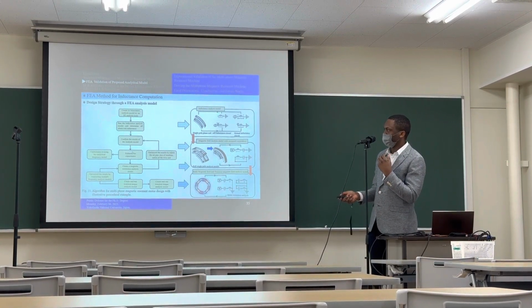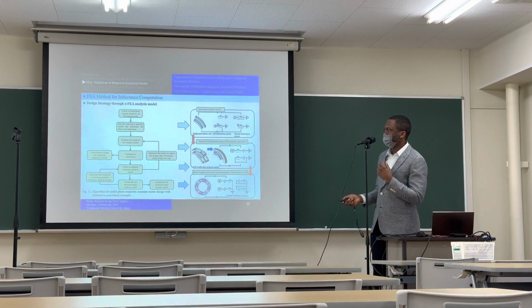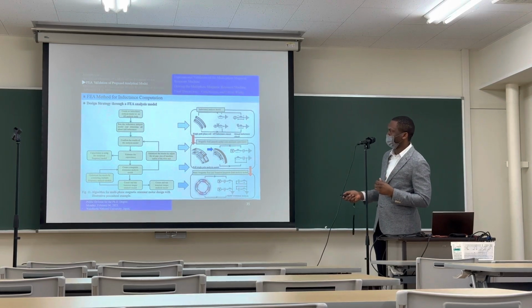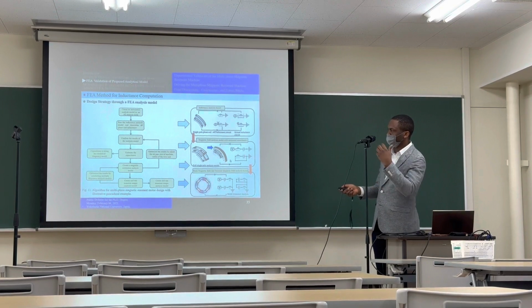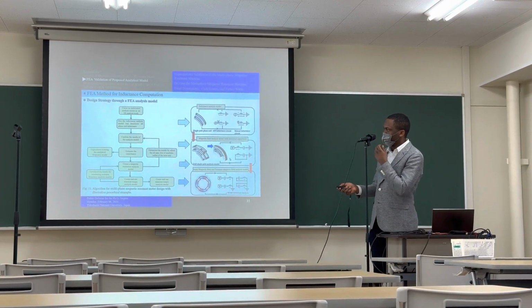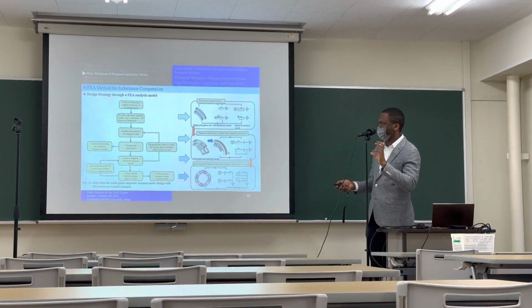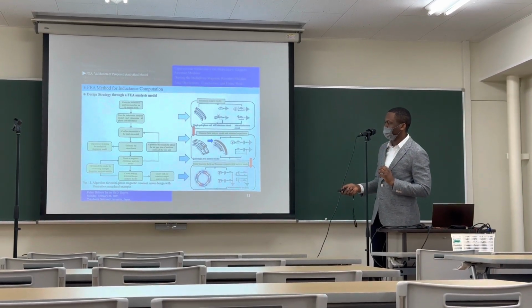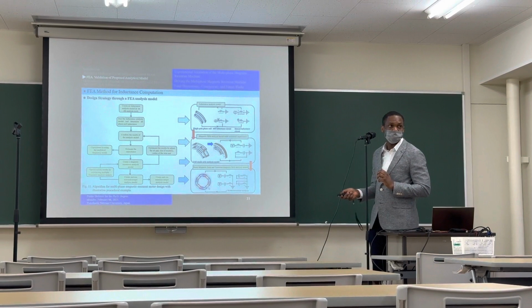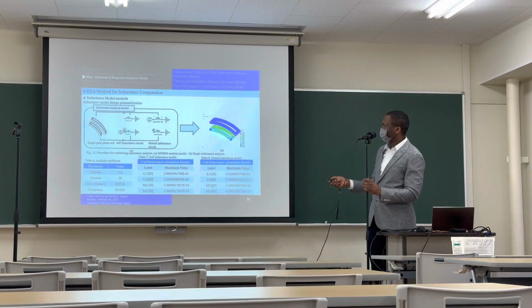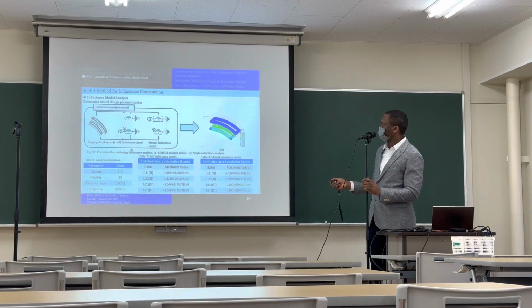When we have the capacitance value, we run a magnetic field analysis. For the magnetic field analysis, the circuit is different, and now we can run a portion of the machine. After running this magnetic field analysis, you can do some sort of optimization, because from it you can study how the machine behaves and change some parameters. After that stage, you run the torque analysis to see the machine in motion.